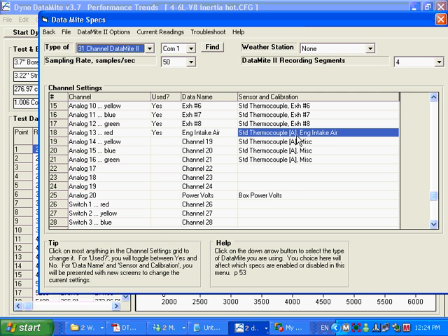Another thing is how you run the test, how you accelerate or control that engine during the accelerating or decelerating part of your absorber dyno test. With an inertia dyno, that is something that you can forget about because the control is so consistent. But with a water brake or an eddy current type dyno, you do have to control things fairly similarly. Correcting for engine inertia effects will help, but it is not perfect. Same as temperature corrections or weather corrections in general. Weather corrections are better than nothing, but they are not perfect.